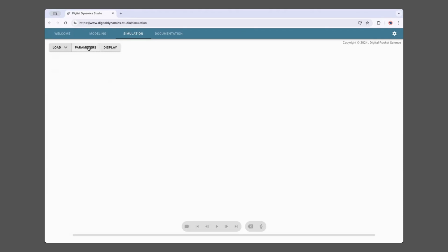And these other buttons here bring up other displays. Parameters. That's your simulation parameters. And that sets what simulation type you're going to do, simulation values, time step size, viscosity, and a few boundary conditions are set here. A few other things. We'll talk about that in a moment, but these are your simulation parameters.